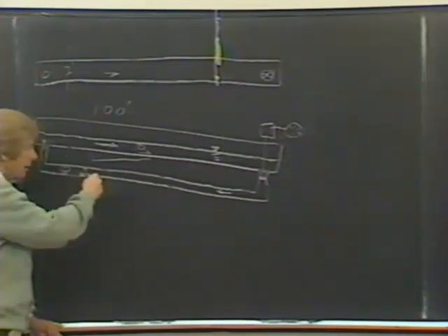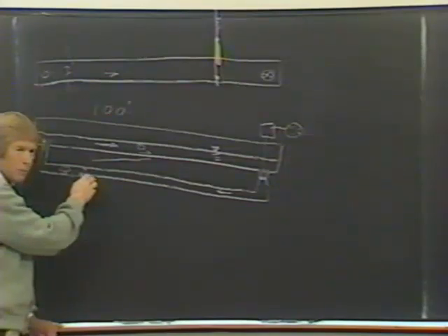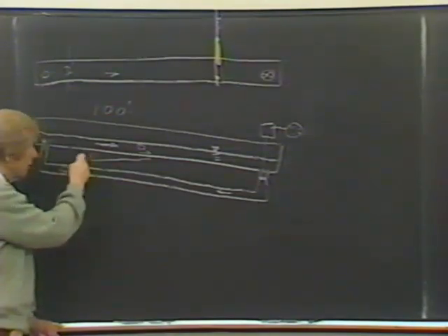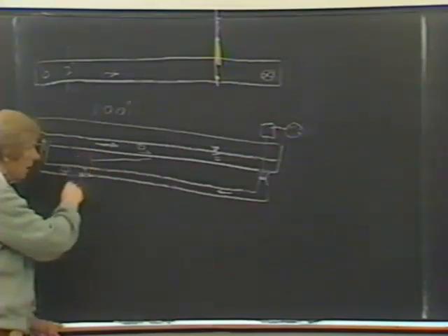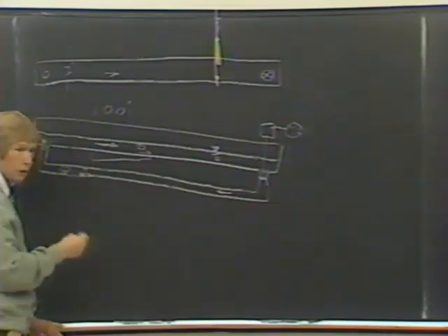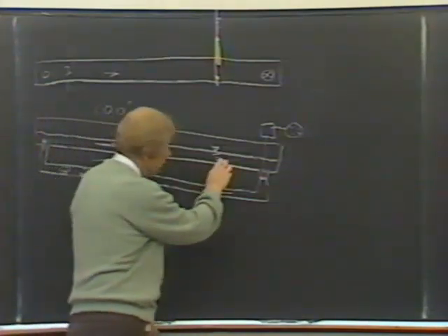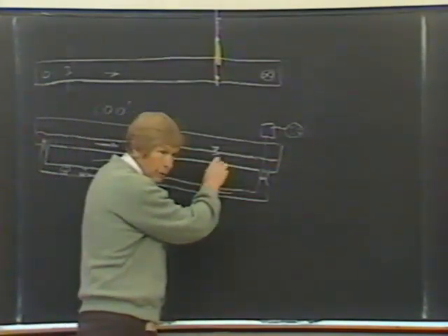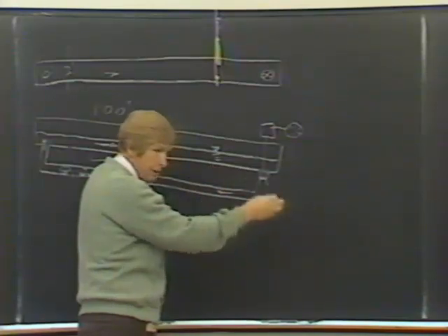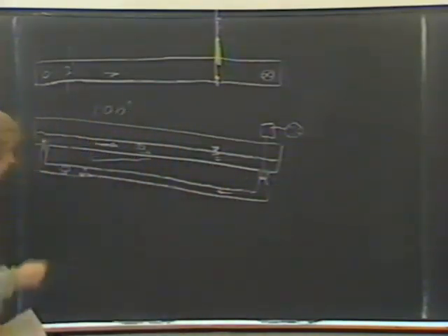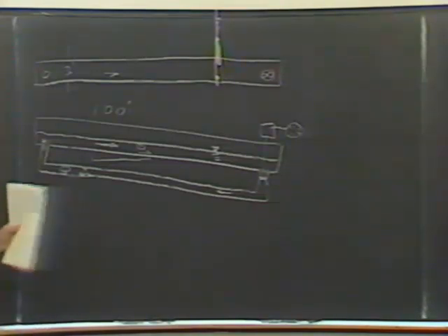some high level, say 3 feet per second in the channel, and stir it all up so that the material is all in suspension. Then reduce the velocity to one such that the material will begin to settle, deposit on the bed, and let it stay at that one velocity for a long time and observe the rate of deposition. Now you all see the experimental conditions, pretty straightforward conditions.